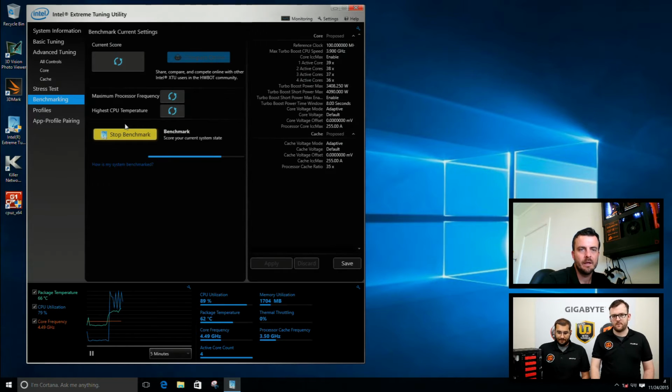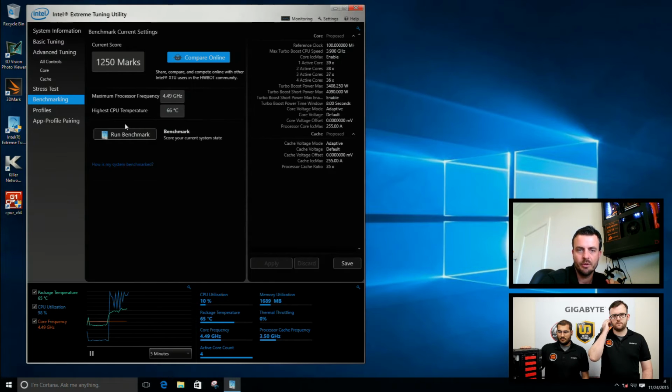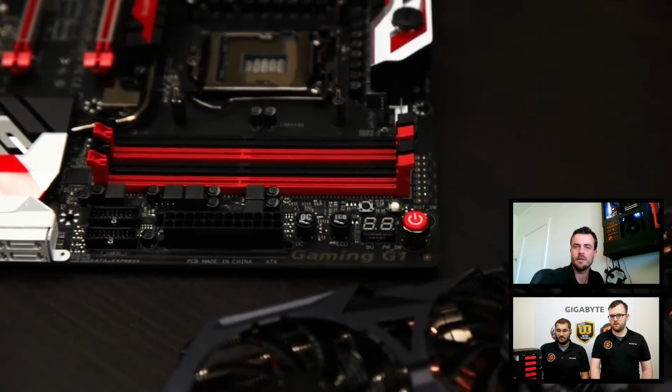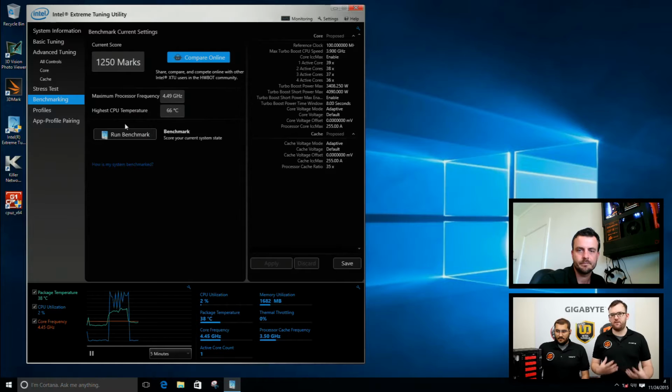Yeah, exactly. So this is how you would, for example, check the temperature that I mentioned before. When you do an overclock, or even when you start with standard settings and run XTU, you can check the temperature of the CPU when it loads up. If at stock frequency you see temperatures above 80, usually it means that your CPU cooler is not mounted properly, so I would recommend readjusting it. When you're overclocking and you're reaching 60 or 70, that's okay, because you are increasing the voltage. It might seem quite hot, but it's still in the safety zone for CPUs.